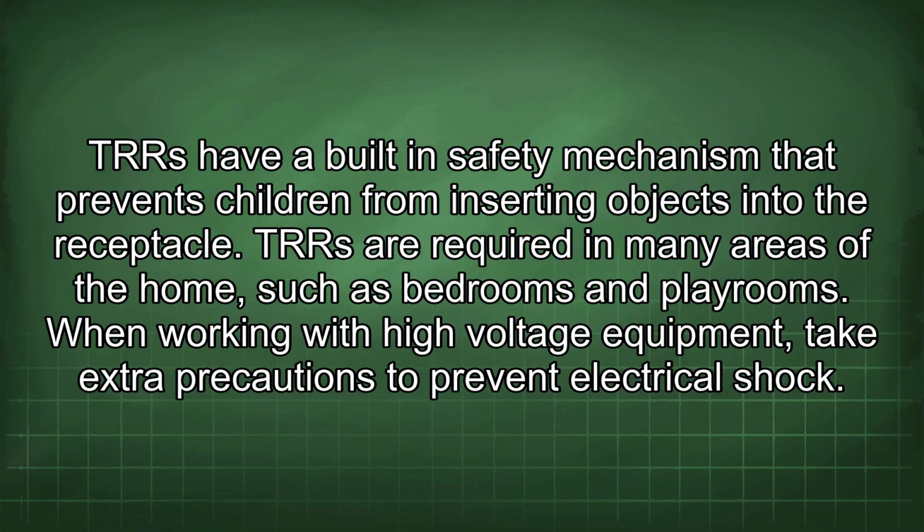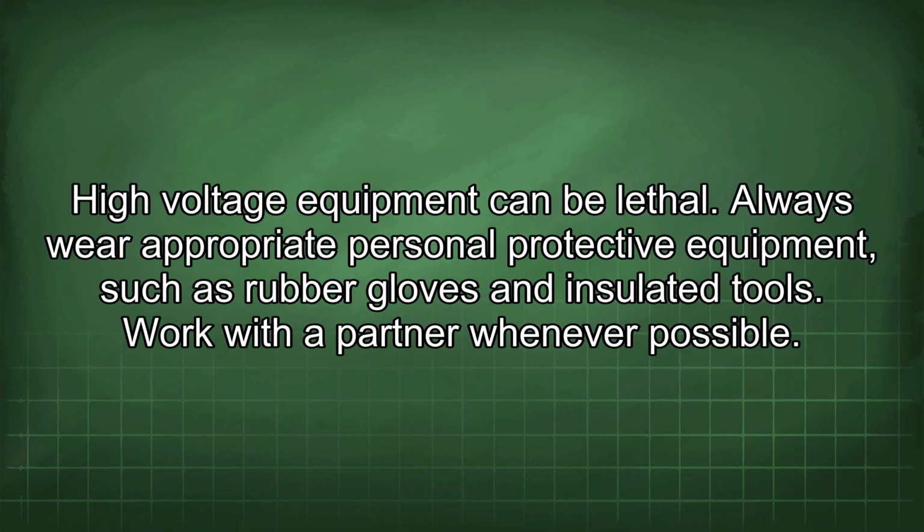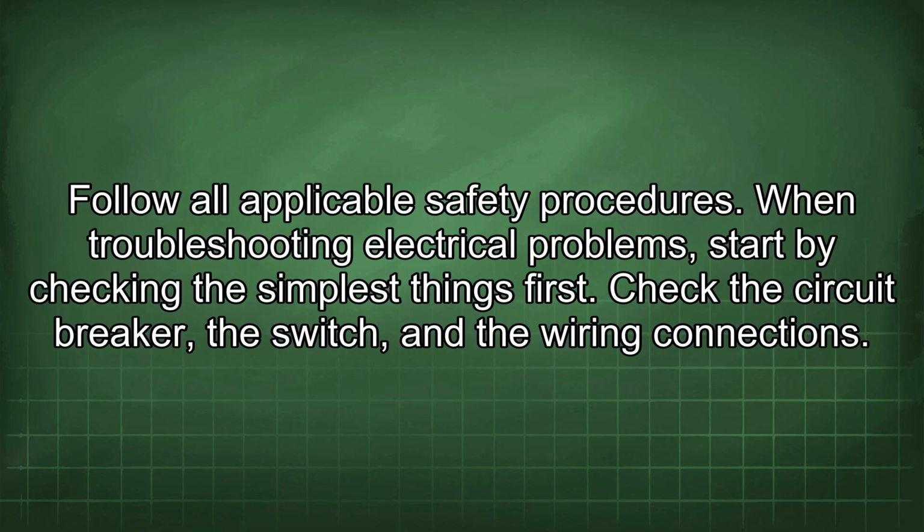When working with high-voltage equipment, take extra precautions to prevent electrical shock. High-voltage equipment can be lethal. Always wear appropriate personal protective equipment, such as rubber gloves and insulated tools. Work with a partner whenever possible. Follow all applicable safety procedures.